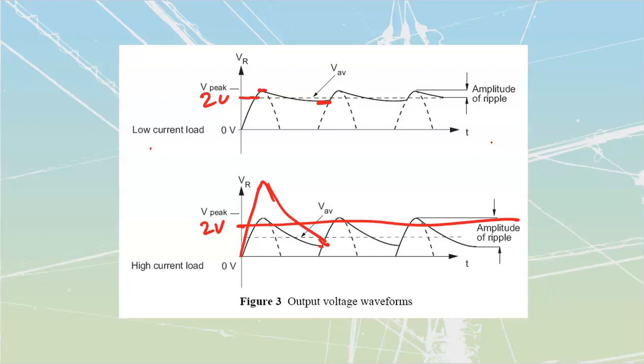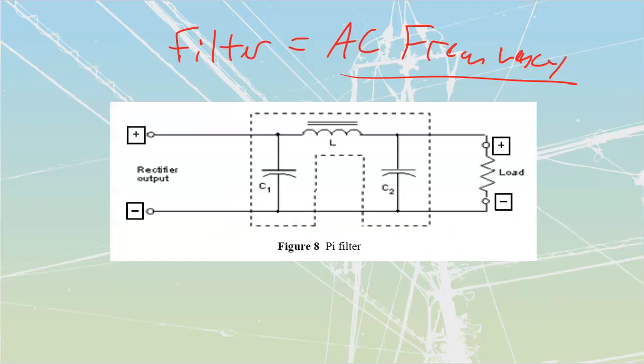Output voltage, you're going to need to design for rectifier peak current limits. That's going to be the maximum current that can go through the actual diodes upstream, and then your load current. The very last thing that I want to say on this whole subject of filtering is that the filters shown here have been drawn in all these circuits attached to a half-wave rectified filter, because it's easiest to see the filtering difference on a half-wave rectified filter.